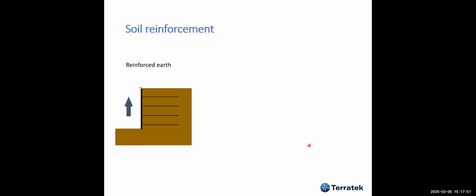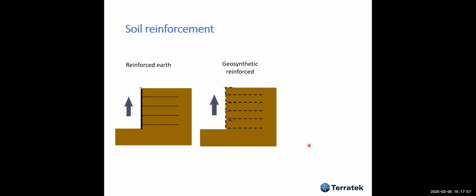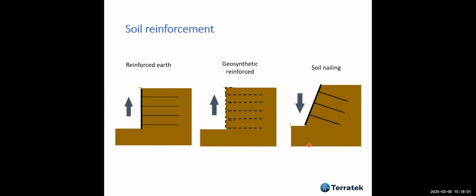It uses compacted material, and you put the reinforcement in as you go up. Okay, geosynthetic reinforcement as well. But soil nailing is just the opposite. We take it from the top down.